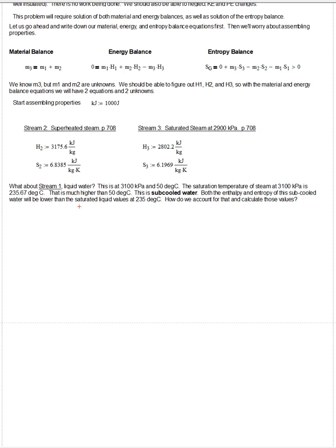I don't know if your textbook has mentioned that term, but that's what we call liquids. Most liquids that we deal with in real life, water that comes out of the tap, and whatever other liquids that we happen to deal with, any kind of fuels or gasoline, motor oil, cooking oil, they are all subcooled liquids. The problem is we don't have steam tables for subcooled liquids. So what do we do? Well, there's a couple things we could do.